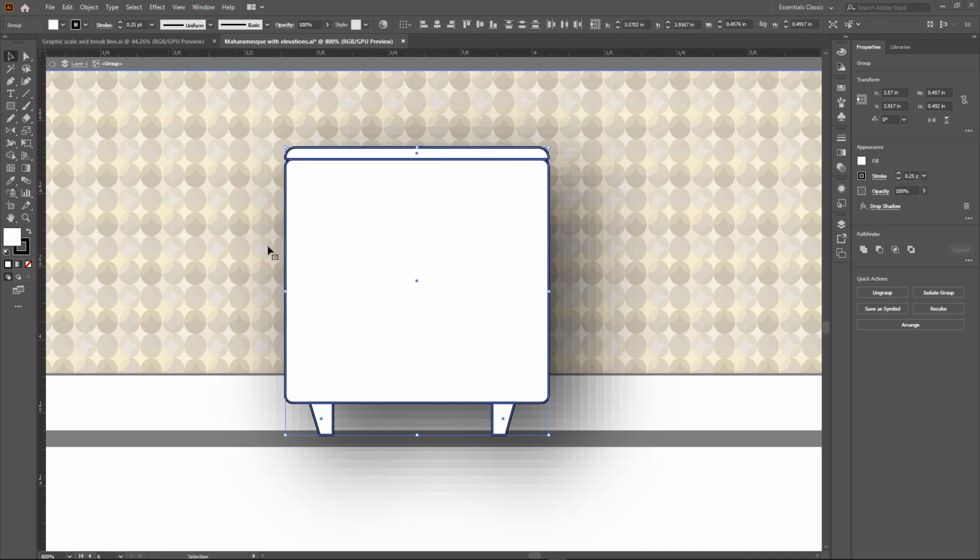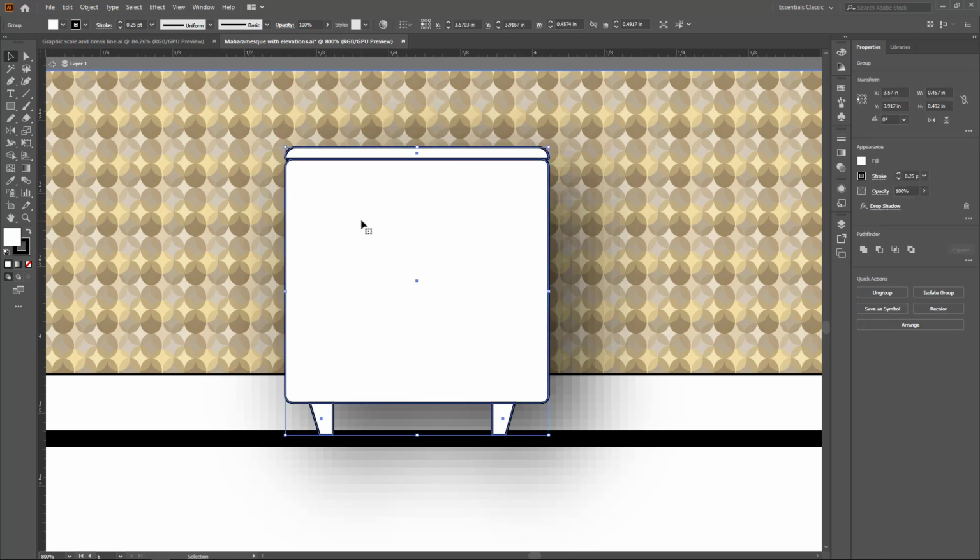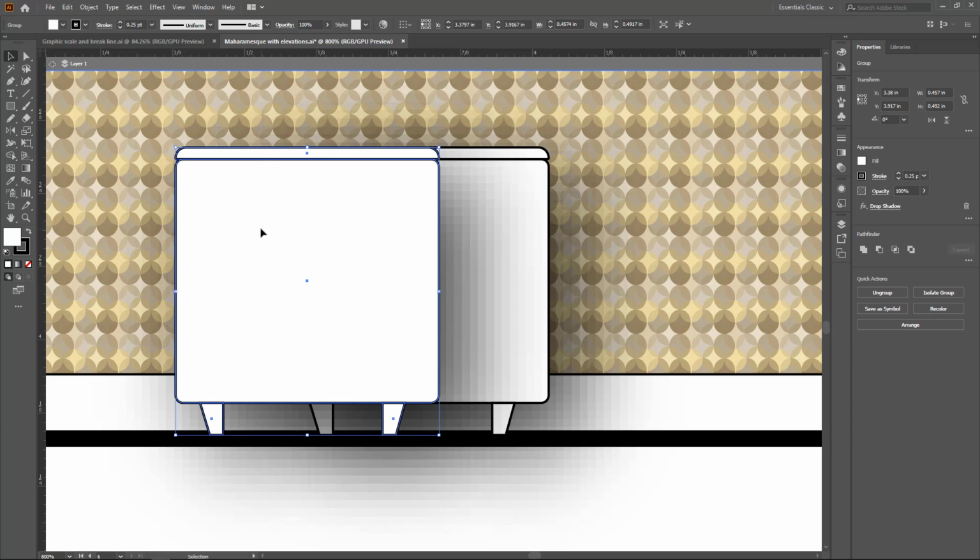This still doesn't solve my problem of painting my pattern onto a solid object. I need to make a white background behind my paint pattern. And the easiest way to do that, I'm going to make a copy of my group. Now, I am inside the group. I'm going to exit the group, select it again, and I could Alt-click drag to make a copy.